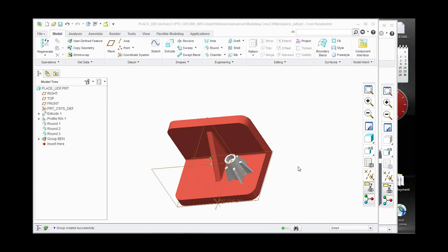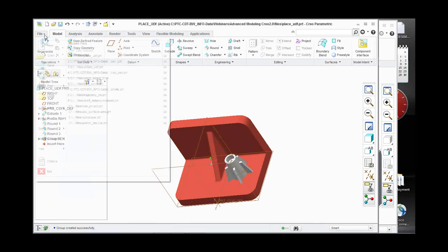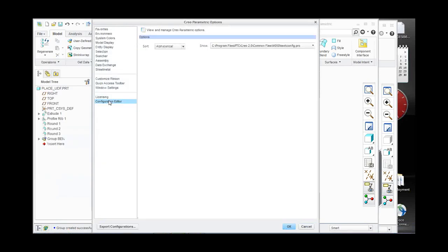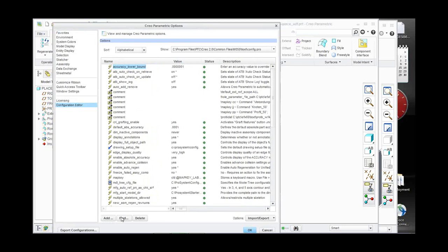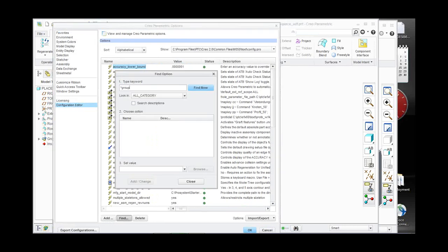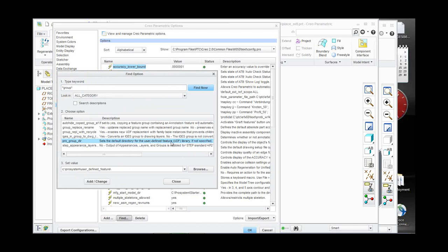How do you save the UDF into the library? There is a config.pro option, guys. One config.pro option that will save where your configs go, or where that does go. I believe it is this one. Pro group directory is where your UDF library comes from. Pro group directory. And then they will save directly into your user-defined library. If not, it goes into your working directory.